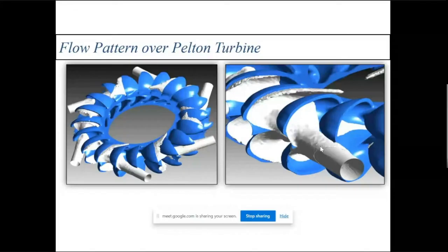So it depends, because a lot of the time people use ICEM CFD for meshing, once we are going for the structured mesh. Sometimes ANSYS Workbench, this ANSYS Meshing, is enough for making the mesh. So it depends on which software you are more familiar with, and the ultimate point is we have to control the quality.